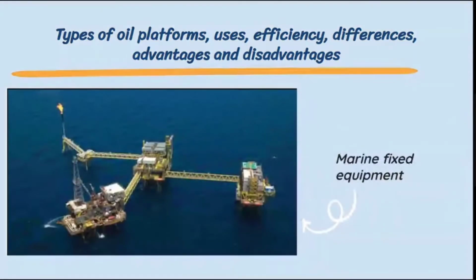Second, the fixed offshore platforms. In shallow waters, it is technically feasible to fix the oil platform to the seabed, this being the reason for calling them fixed platforms. The columns that support the decks with the production equipment and facilities can be made of concrete or steel, which run from the surface platform to the seabed. Here they are fixed with larger concrete structures.